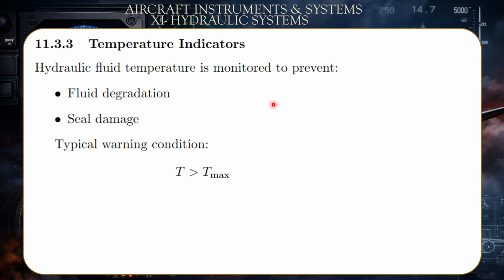Now when you have a cool temperature, which is acceptable, it shouldn't be too cold, by the way, but a moderate temperature, the conductive material within this resistance would be close to each other, allowing more current to pass through. This is how you can interpret the fluctuation of current as fluctuation of temperature and derive from it the exact value of the temperature at that moment.